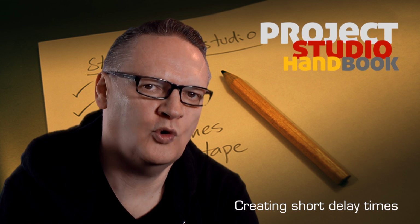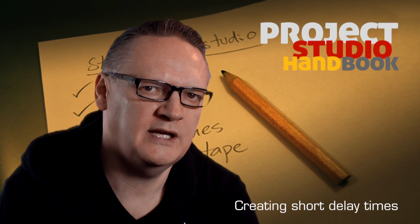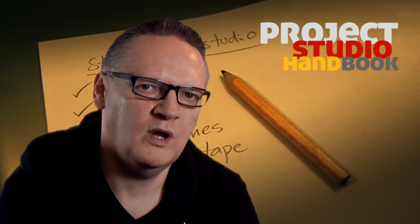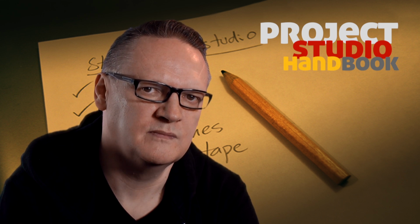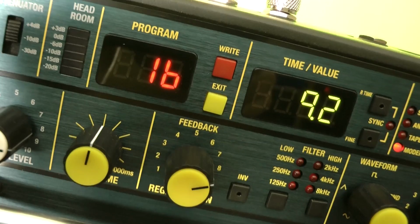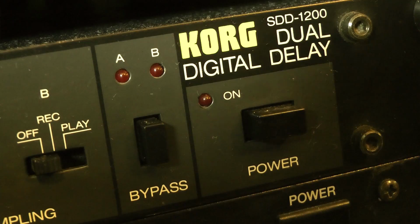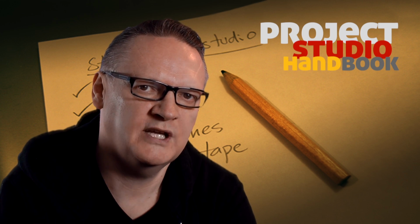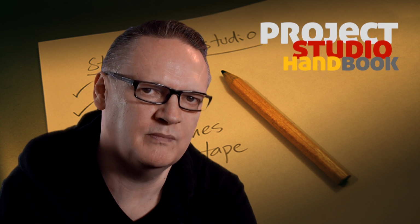Phasing, flanging and chorus use the shortest delay times of all time domain effects, typically between 1 and 30 milliseconds. Analog solid-state and digital delay lines are capable of these short delay times, but most tape recorders are not. It was therefore necessary to employ a different technique to produce them.